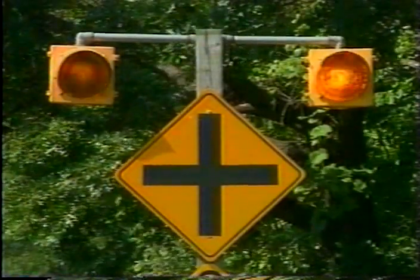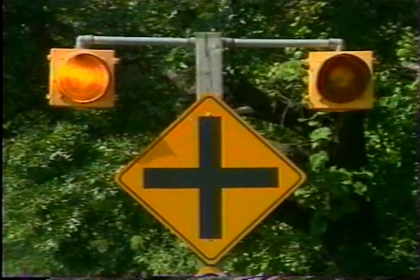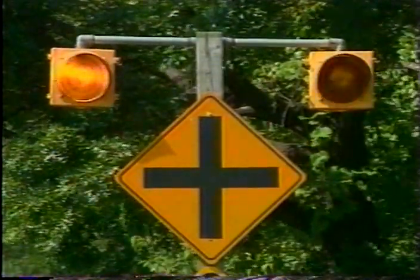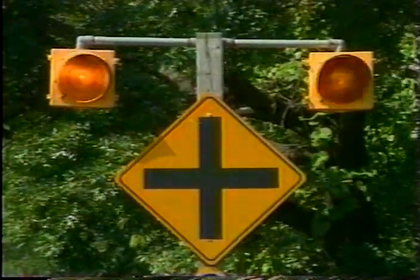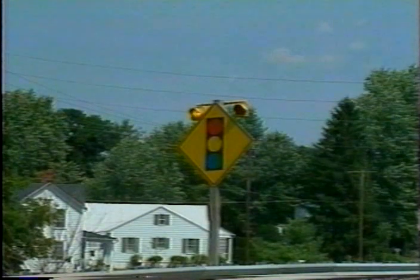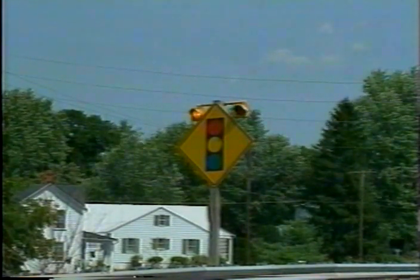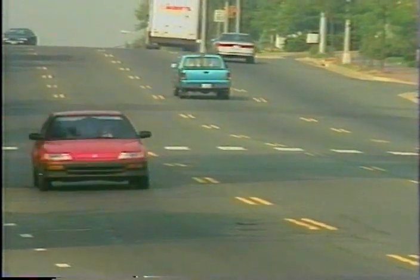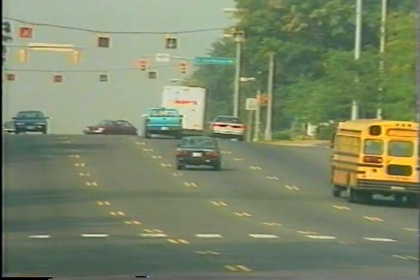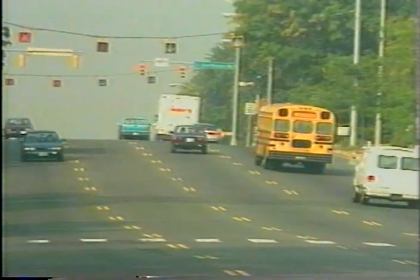In this program, we have covered special use traffic controls. They include the beacon, one or more sections of a standard traffic signal head with a flashing yellow light in each section. The beacon is designed to warn drivers of special situations or to draw special attention to speed limits. Lane use control signals, overhead signals that control specific lanes. They are most commonly used for reversible lanes.